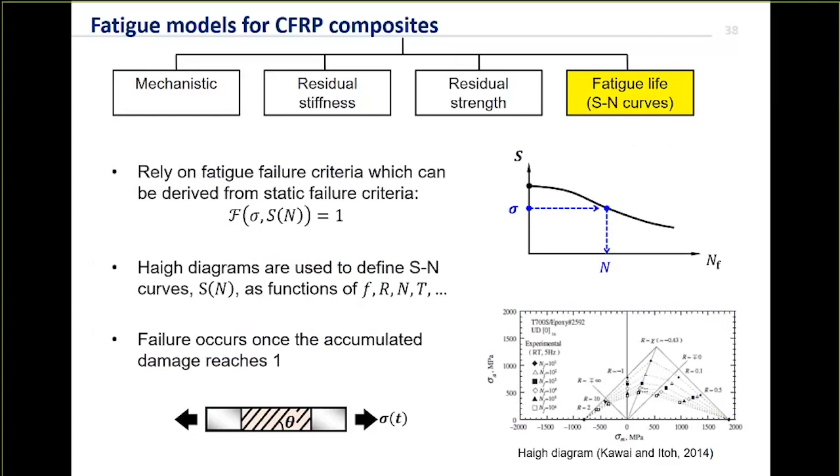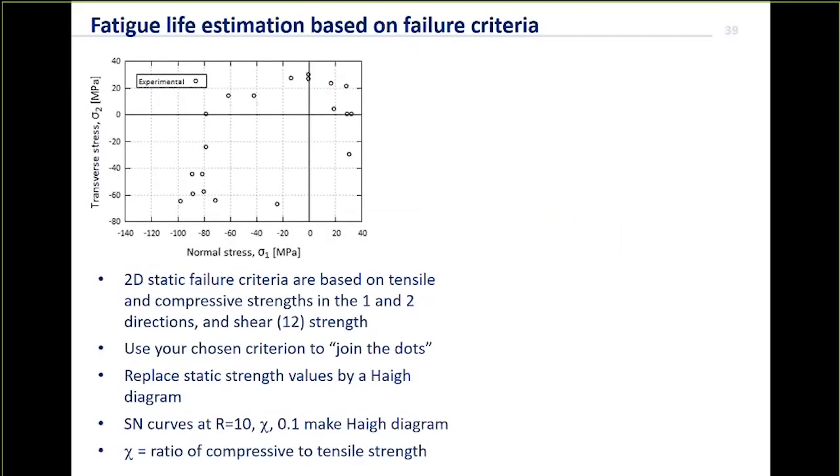In between, you have a couple of other options as well, which involve tracking damage variables and seeing how the strength and stiffness of the structure evolves over time. But again, these involve having nonlinear damage models embedded in the finite element solutions. So they're still analytically pretty heavy. So let's look a little bit more at this simple fatigue life approach.